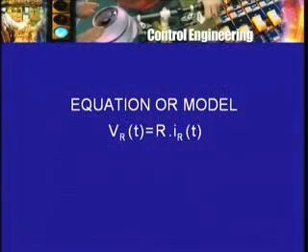And we are making the assumption here, this is the important fact that one should be aware of and note, that this physical thing can be described, or part of its behavior can be described by means of an equation like VR of t equal to R IR of t, where in this case R would be the number 1.3 into 10 raised to 3 if I is a number which represents the current in the resistor in amperes, and VR is a number which represents the voltage across it in volts. And so you have volts equal to ohms into amperes.